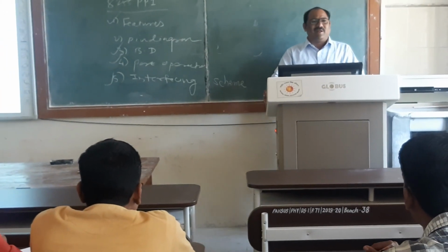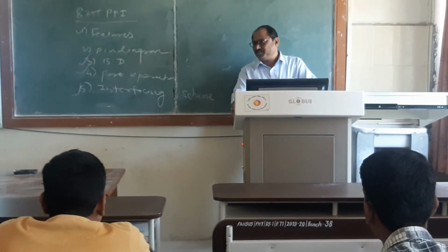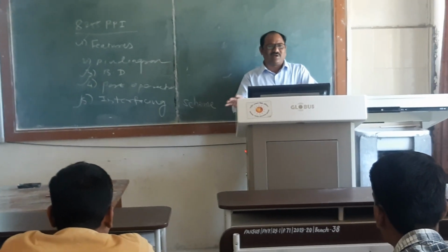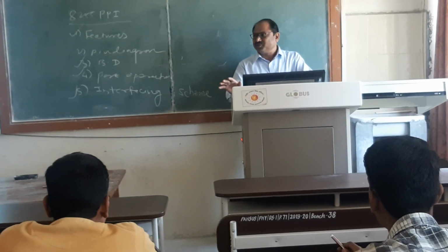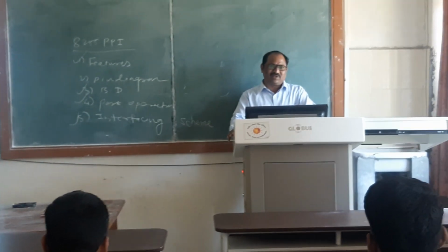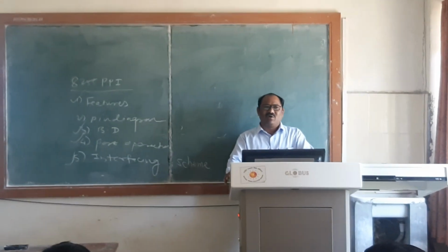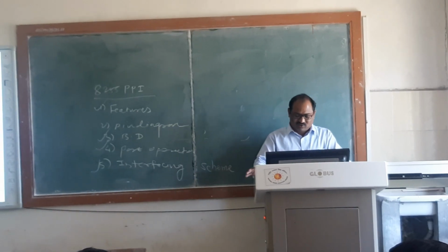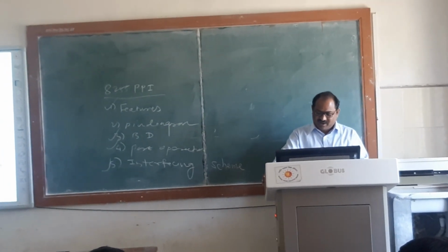Now, there are 6 modes of operation. There are 3 counters, and the 3 counters work independently. Each counter is 16-bit, and there are 6 different modes of operation. You can program these 3 counters independently through these 6 different modes.